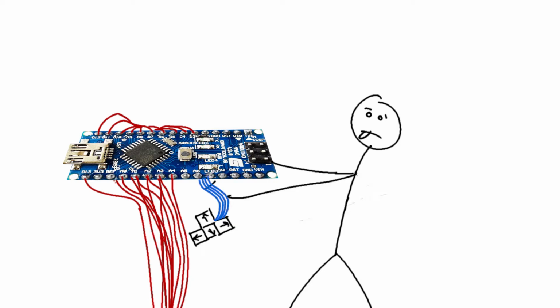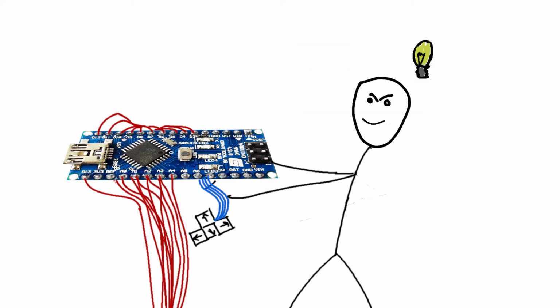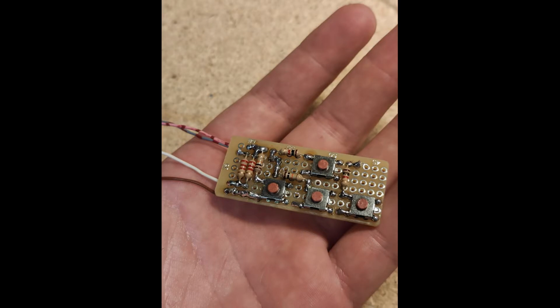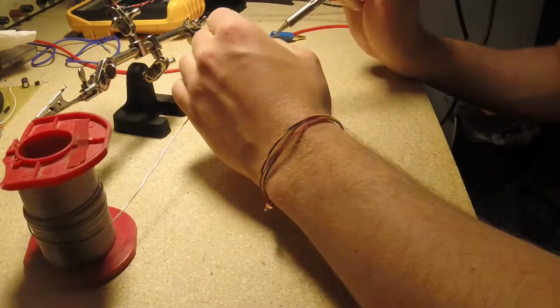The next thing was the keypad, and as mentioned before, we can't use 4 of the input pins, since sadly they are already occupied. So I came up with a great plan and I forged this incredible schematic, which basically makes it possible to use 4 buttons with just 2 wires. Yeah, I mean simple voltage divider logic. And let me tell you, the process of making this damn thing took me over an hour.